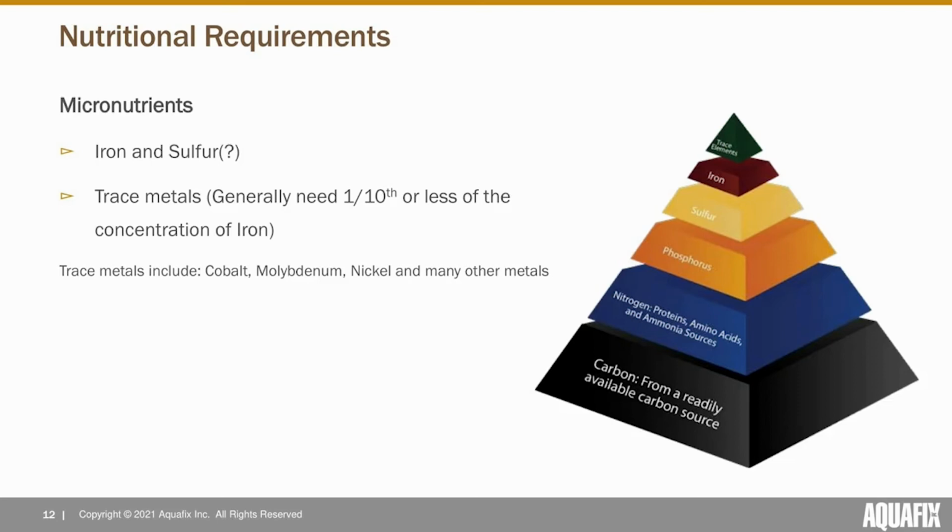Or you might have nitrogen coming in some of the time, and a lot of the time your influent sludge feed is low in nitrogen, but if you look in your digester, you'll notice there is an accumulation of nitrogen taking place, which means you don't have to worry too much about nitrogen deficiency. So I would say good to consider both, but generally the influent is a more important variable, assuming you have an ability to take a good representative composite or you sample regularly enough to have a good understanding for how your influent varies throughout the year.